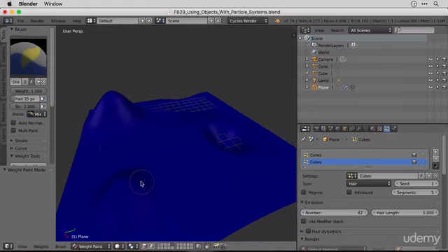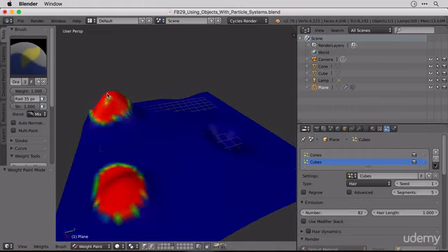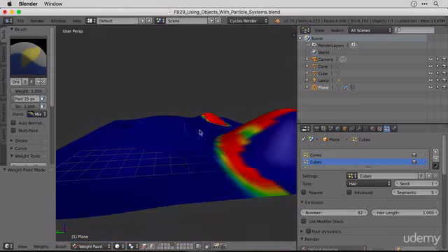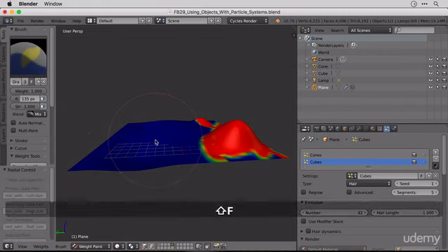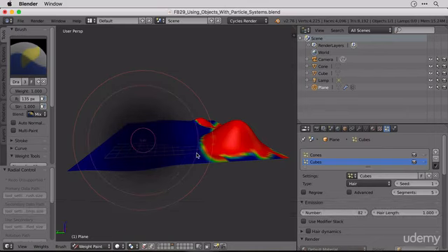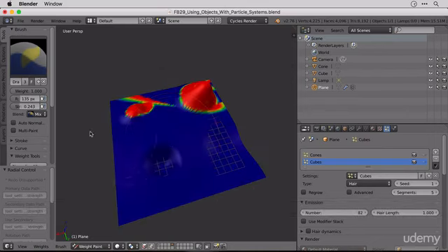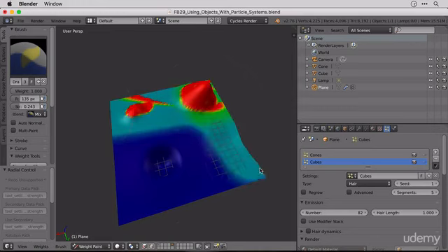And so we've got these two hills, so I can paint on that hill, I can paint on that hill, and I'll probably have to spin round and paint the other side of the hill as well. And then I'm going to reduce or increase the size of the brush and reduce its strength down to 25% or thereabouts. Yeah, that's fine. And I'm just going to go over there, over here, over there, over there once more. There we go. So that should help control the distribution of our cones and limit it to only these areas, leaving the blue area clear.